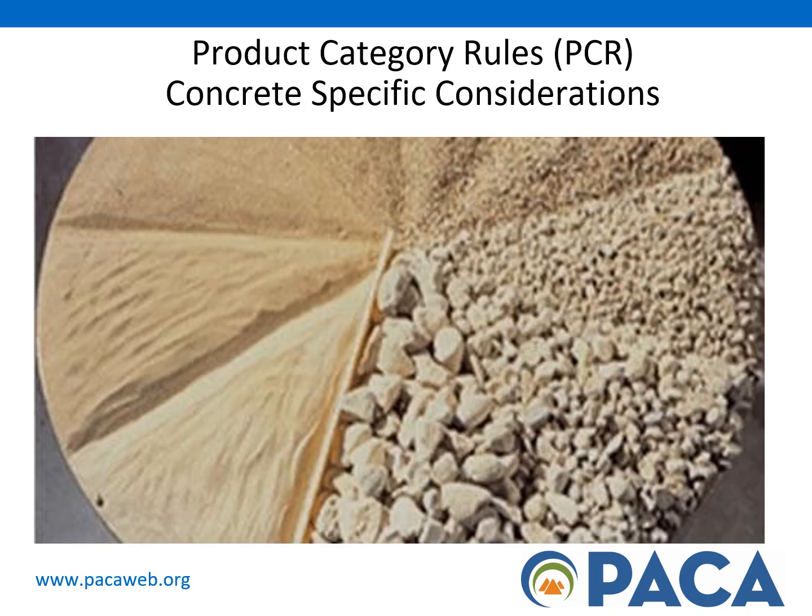The product category rules for concrete have very specific considerations. We look at ingredients, production methods, transportation, and performance requirements. Ingredients include the impact of the cement, aggregates, water, and admixtures on environmental performance. Production methods measure the variations and impacts based on production techniques and efficiencies. The effects of transporting raw materials and finished products must be considered, and the performance requirements are balancing the environmental impact with structural and durability requirements.